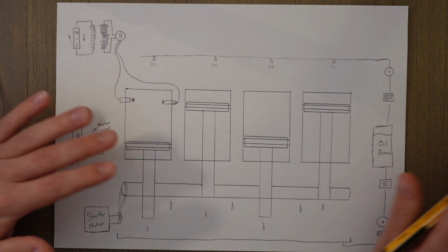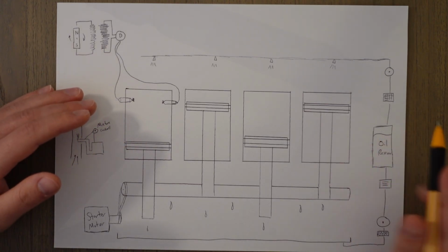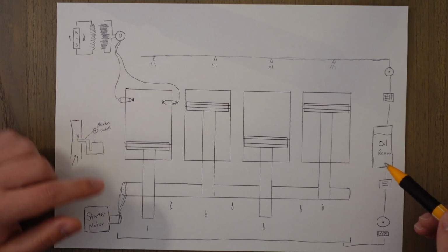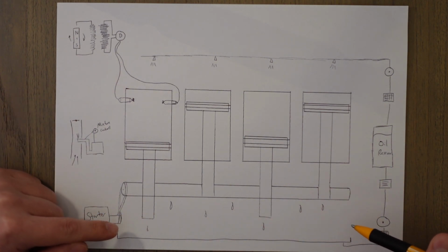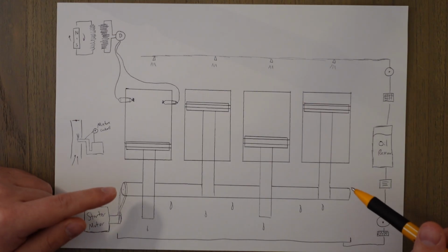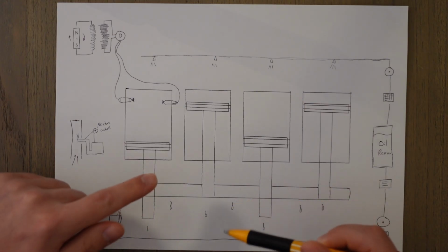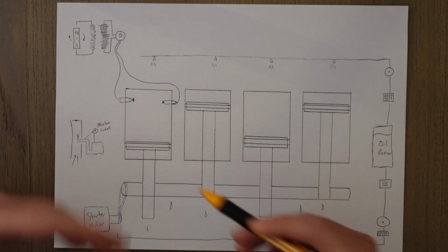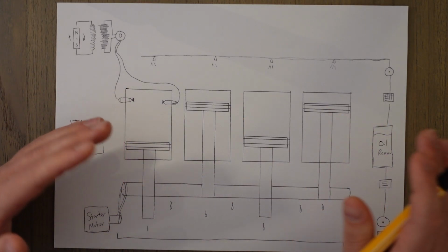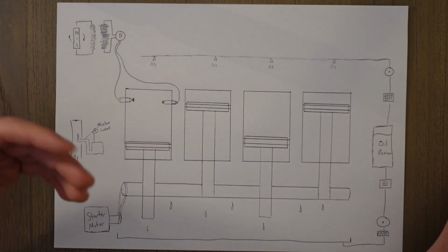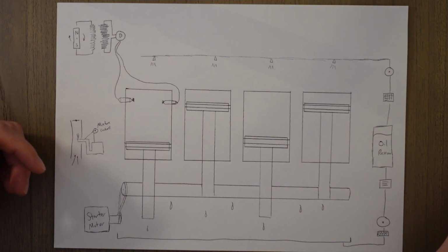If we have a wet sump system, we basically eliminate the need for this reservoir, and all the oil is housed in a sump at the bottom. It will probably be a lot higher and a lot deeper because the crankshaft actually rotates in the sump and it splashes oil around the engine. Both have their uses in aviation, and your aircraft will probably have one or the other depending on what the manufacturer thinks is most appropriate.